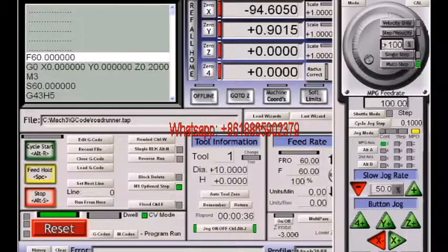This percentage reading here is not used at the moment. It is part of the old step velocity mode, which will again be replaced. There's a calibrating button here to calibrate your MPG, to tell the system how many encoder counts it will get per detent of the wheel and so on, and it'll calculate things out to make it work smoother for you.